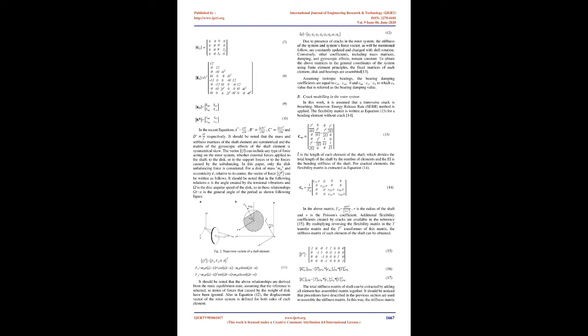In addition, the Fourier spectra obtained by FFT were used to investigate the internal frequencies corresponding to the typical orbit characteristics. The results showed that the appearance of the inner loops and orientation change of whirl orbits in the experiment agreed well with the theoretical results obtained previously. The presence of higher frequencies 2x, 3x, 4x, and 5x in the Fourier spectra showed the causes of subharmonic resonances at these subcritical speed zones.